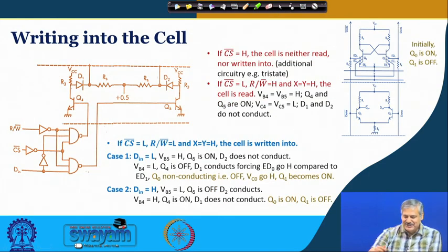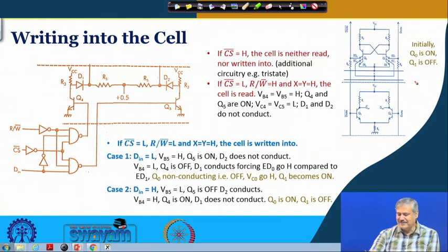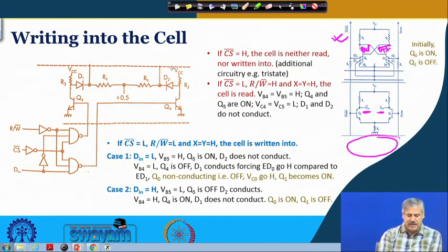Okay. So, the circuit that you can see now, this is the basic memory cell, okay, and generally we consider this is on, Q naught is on and Q1 is off, right, and this is the data line or the bit line, okay, and this is the reading or sense amplifier. So, this is D out bar and this is D out, which we have already seen. Now, here in this place we are having this particular block. Okay. So, this is extended to this particular side.